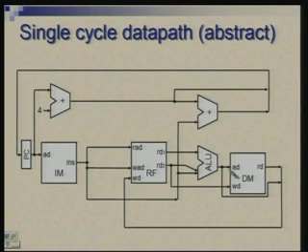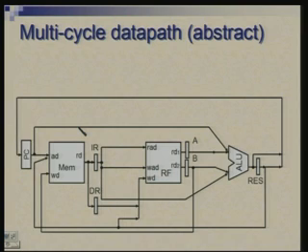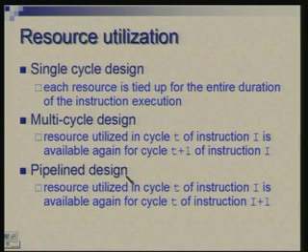So, register file, ALU, data memory and 2 adders, whereas in the multi-cycle data path we have a single memory, register file and ALU, and registers isolating these. So, now let us look at a more precise comparison of these two.